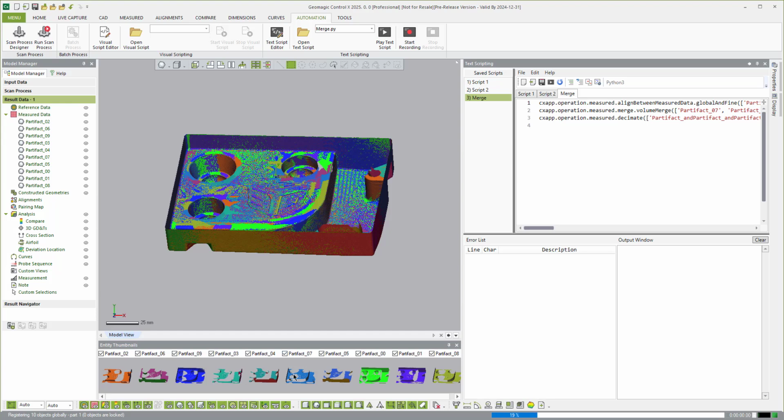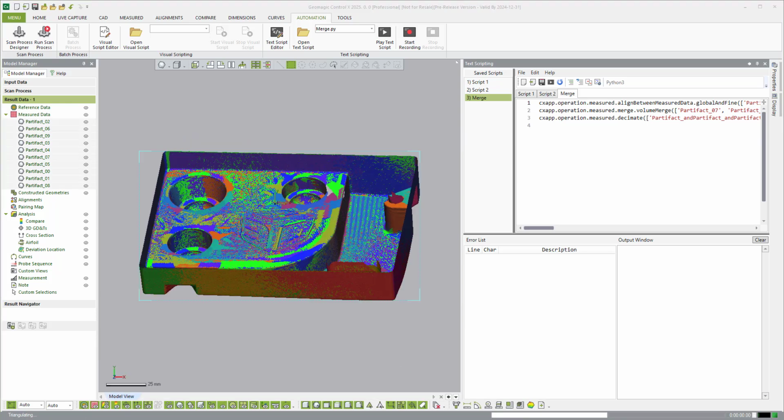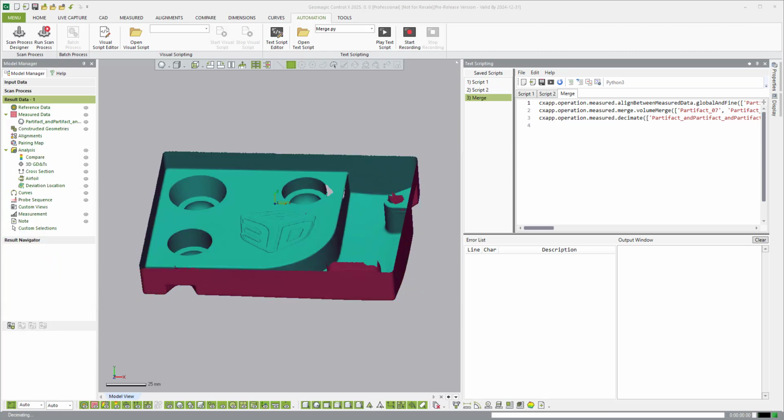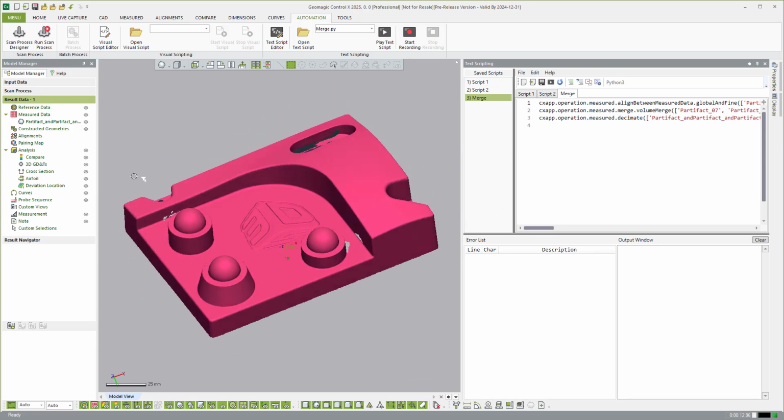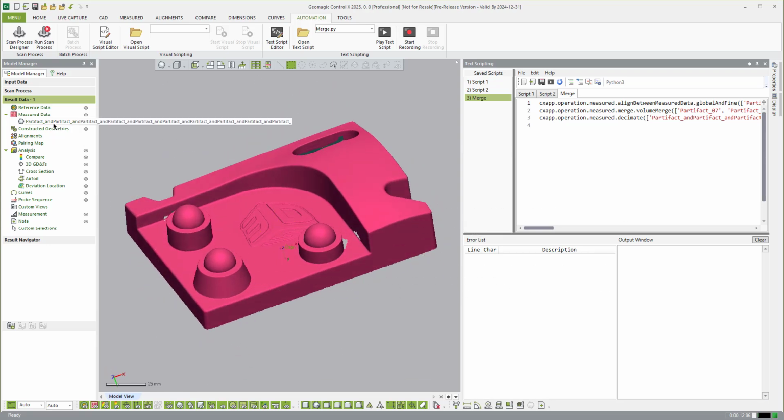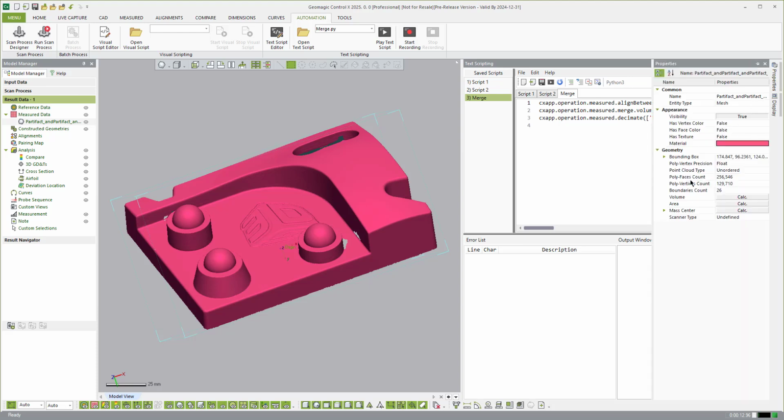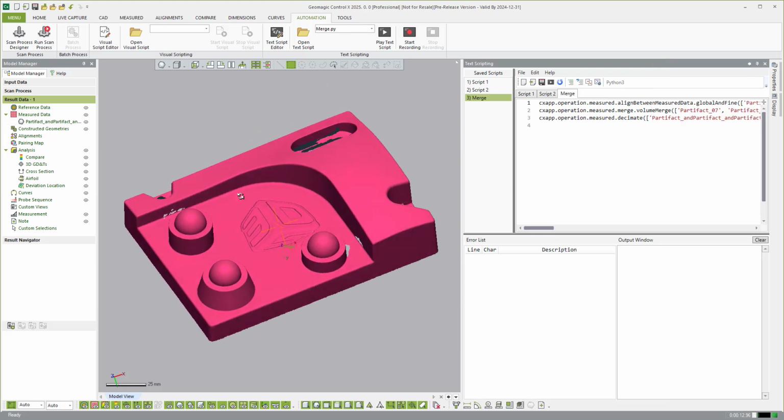And you'll see it goes ahead and runs through the process of aligning the objects, and then we'll jump over to merge. Yeah, so it's still registering right now. Now it's triangulating here. You'll see down here at the bottom. Now you see that it's decimating over here. And now it's complete. So we just look at the scan. I can click on it, go to properties here, and just see that it's very low polygon face count, 256. So it went ahead and decimated it as well.